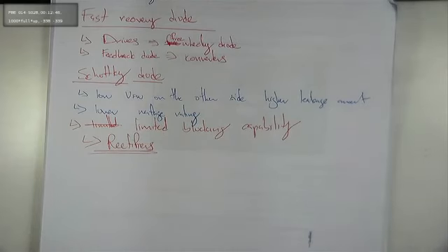So now you see where the three different types of diodes are used. Power diodes are used in general. Then if you require fast recovery diodes, you can use those. These are used for freewheeling and feedback types, drives and converters. Then we have the Schottky diode, which we normally use for rectifiers because of its characteristics. So you see, we cannot use one particular kind of diode for all applications. We have different types of diodes for different types of applications. So you need to know where you are going to use which diode. You cannot just take a diode.